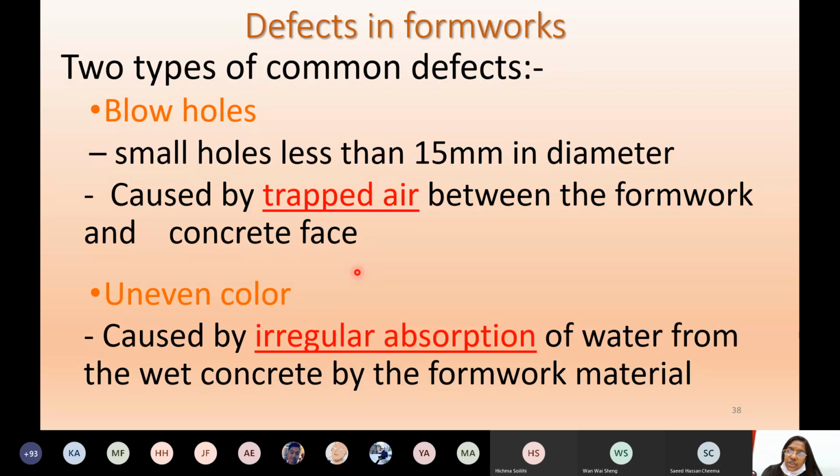All of you know that the formwork is made exactly the same size as the beam or column you're going to use. It is the design value, right? You cannot reduce or increase that value. You can increase, on the safer side. Although you lose material, it is safe. But if the size is reduced, there's a chance of failure, and a chance of other types of problems for that particular member.